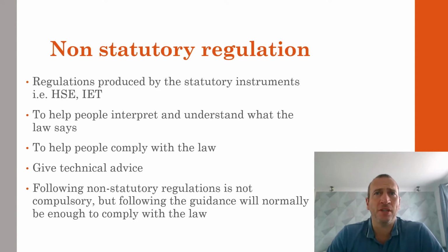We previously mentioned the HSE, but as electricians, the IET, that is the Institute of Engineering and Technology, produced the BS 7671 regulations for use in electrical design. These non-statutory regulations help people interpret and understand what the law says in the Electricity at Work Act, among other things. To help people comply with the law, they also give technical advice. In short, following non-statutory regulations is not compulsory, but following the guidance will normally be enough to comply with the law.